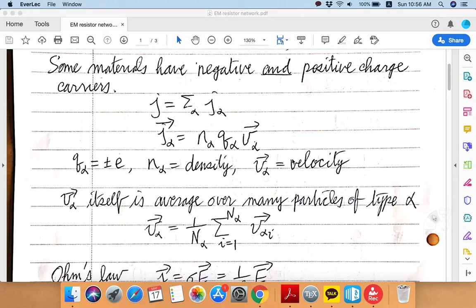And the holes are, although fundamentally they are the electrons, in all aspects of their behavior, they act as if they were positively charged particles, not negatively charged particles. So what that means is that it's much better to treat a hole as if this is a charge plus e carrier rather than a charge minus e carrier.